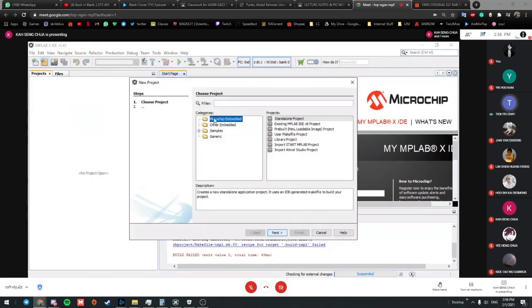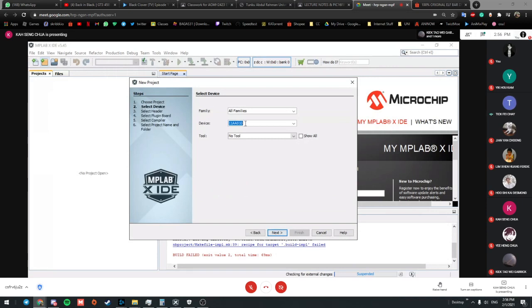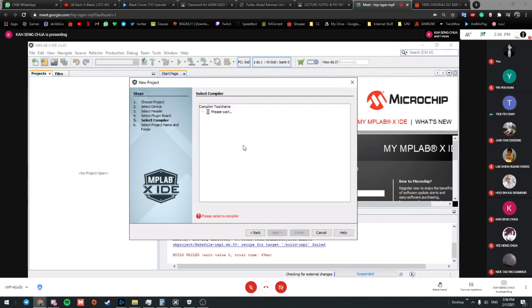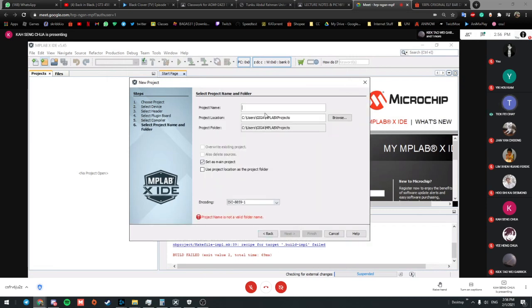Let me see the config. Okay, new project. Standalone project. Click standalone project, next. 16F877A. Okay, next. XC8, next. Then you name it W3, Week 3, whatever. Okay, next, finish.